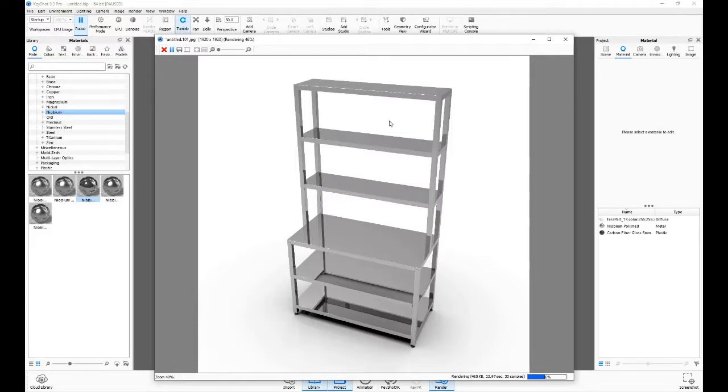So for an example, if the project number is project number 1, it's going to say 1, then it'll have a space. If the opening width is 1600, it'll say 1600 wide, and then it'll say what the working load is. So say for instance it's 1500 kilogram safe working load, and that'll be the actual file name for this part. So I'll go ahead and say OK.